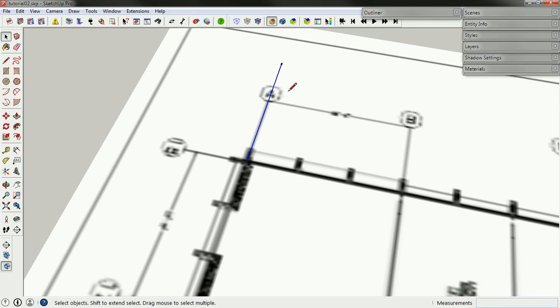And now I'm going to take that and move it, and the shortcut for move is M. That's what I'm going to do here. And to move something, I can click on it, and if I press Control while I move it, I can copy it. So if I press Control again, it just moves it. If I press Control again, as a toggle, it copies it.